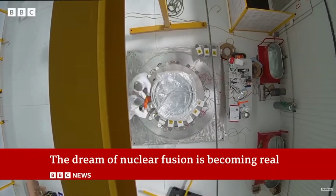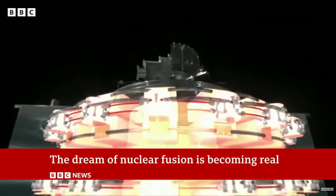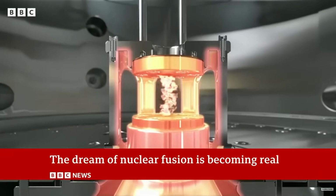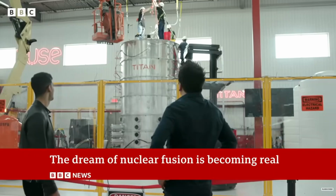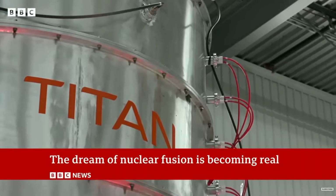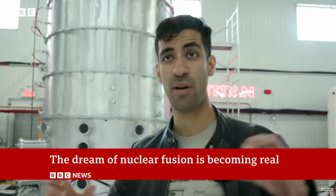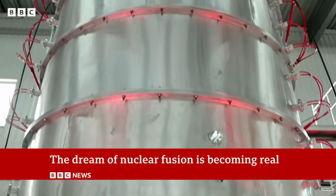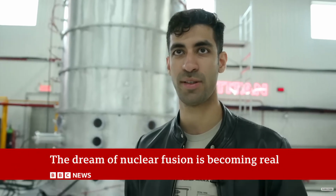They've built Titan, a pulsed power driver capable of producing lightning in a bottle, the equivalent of 800 strikes at once. And this is Titan. Whoa. Check that out. Yeah, it's a 1 terawatt. The key innovation here is how do you trigger 238 of those bricks within less than 2 nanosecond delay or jitter between them. And that's kind of our core technology, being able to build that triggering system.